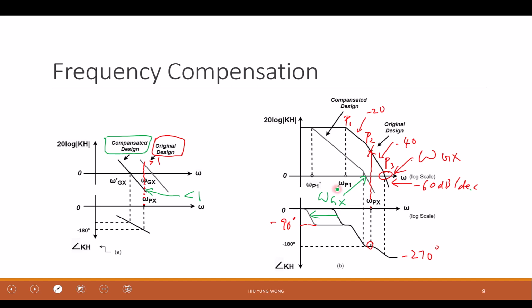Is this okay? So basically the idea is that I move the first pole, like what you suggested. But earlier when you suggested I only have 1 pole, I just tried to trick you. I said that, isn't it that if you move the pole to the left, both the gain and also the phase will be shifted? It's right. But there is only 1 pole, and there's no oscillation anyway with 1 pole. Here, this is exactly what you suggested.